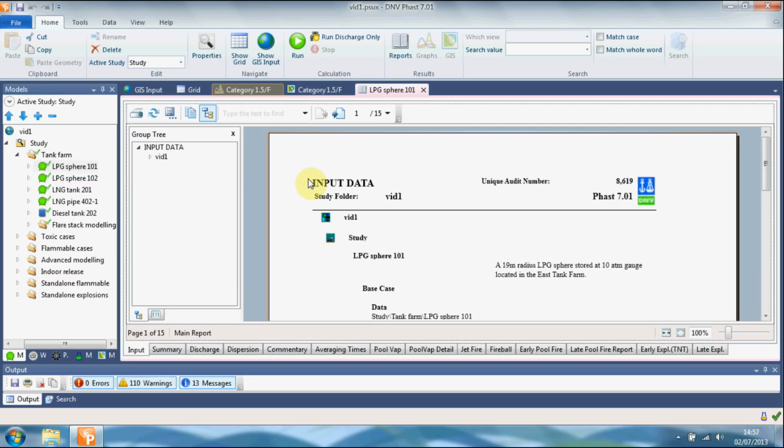You can have many graph views, GIS result views, and report views open at the same time. However, it is best to close a view once you have finished using it, as it will reduce the risk that the program will have problems with low memory. Similar to the graphs view, the report view will normally contain several types of result present in different tab sections. A given tab section will present the results for all the weather conditions that have been processed for that scenario.